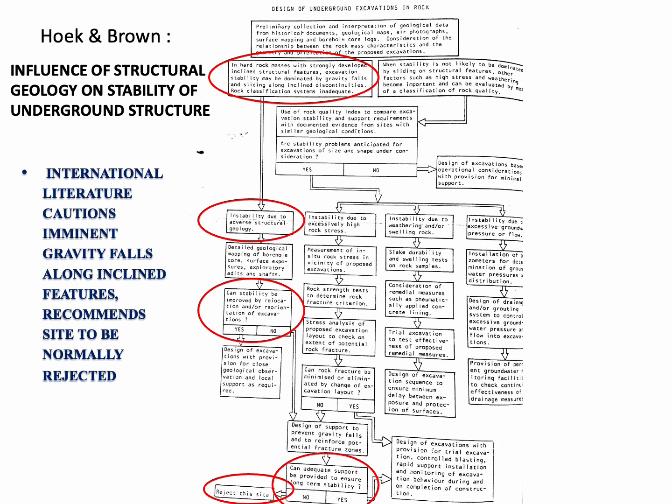That means if relocation could not be seen to be improving the stability conditions, and also if no adequate supports can be designed to ensure long-term stability, then if no, Hoek and Brown suggest that this site needs to be rejected.